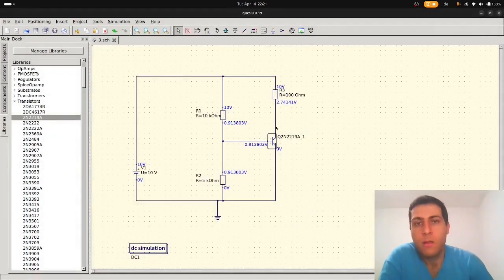And then now I have a good amount of collector voltage, which puts this PN junction between base and collector in deep reverse. Okay, so when it is in deep reverse, it means that it's like saturating the PN junction into reverse and just shooting incoming electrons from the emitter over to the collector.